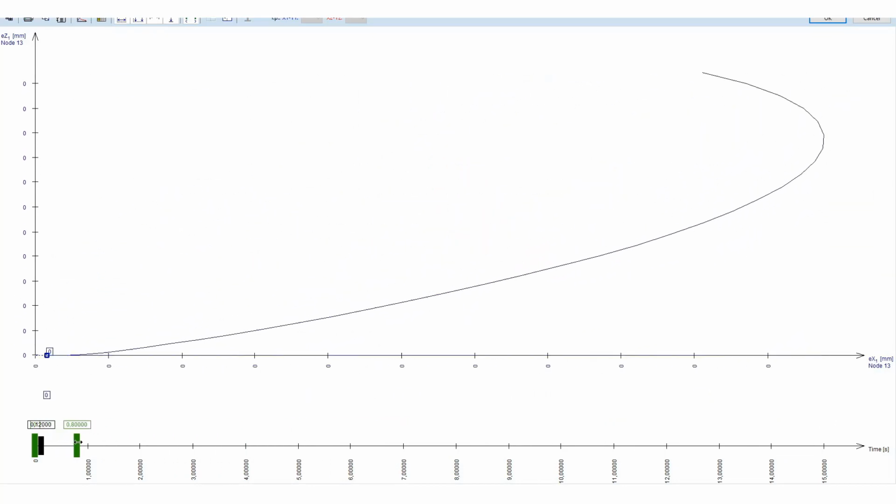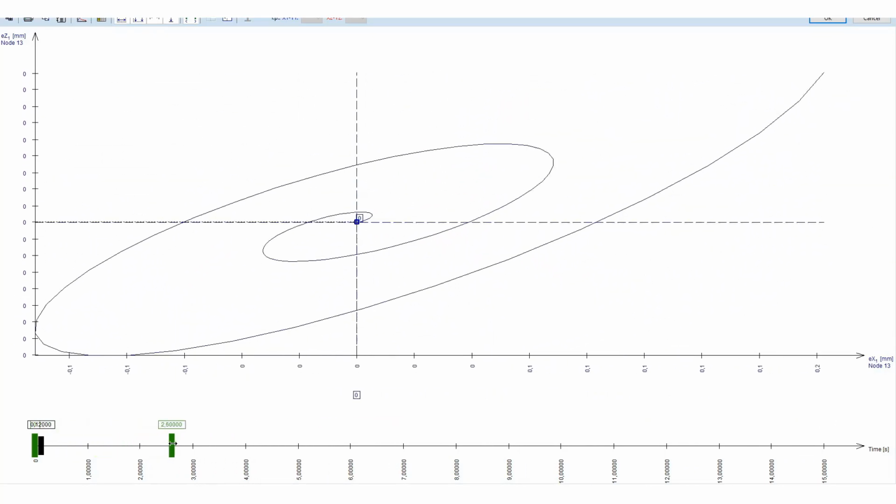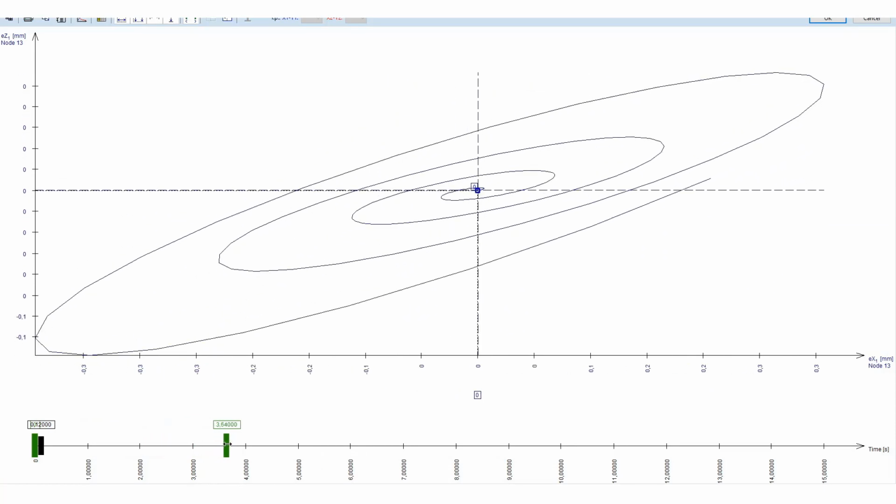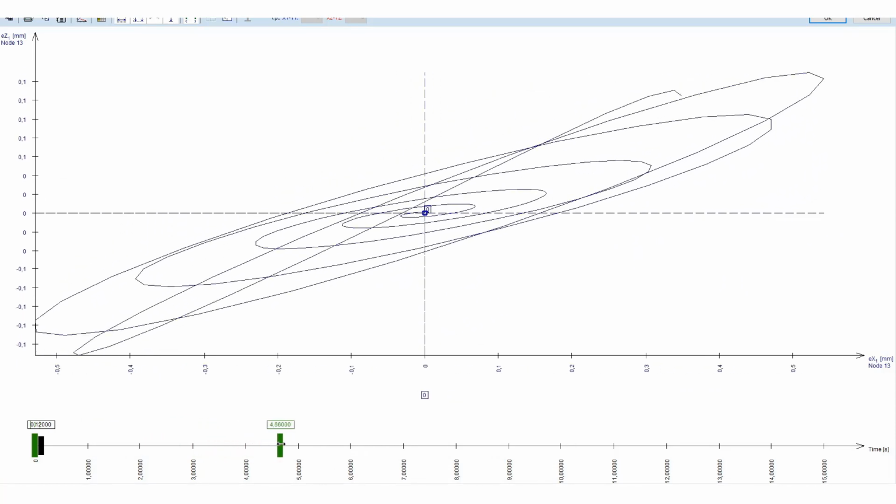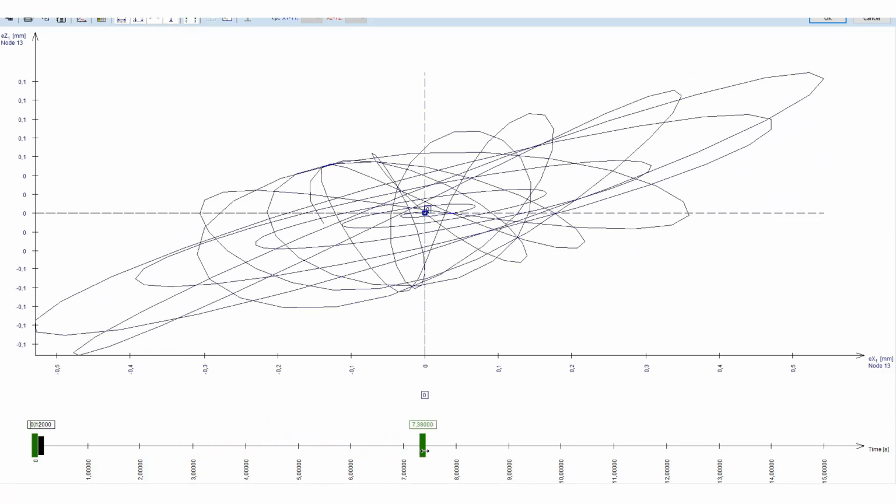As we can see, the rotation movement caused by the machine is increasing like a spiral, then gets chaotic as we reach the natural frequency of the structure. After that, the movements are stabilized and we get an elliptical curve, which is a typical response to a harmonic excitation.